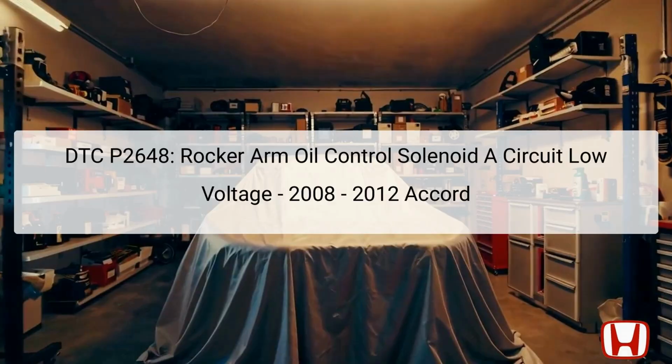The DTC P2648 indicates a malfunction in the rocker arm oil control solenoid A, specifically on the intake valve side, for 2008 to 2012 Honda Accord models. This code often relates to the vehicle's variable valve timing and lift electronic control (VTEC) system, which is critical for optimizing engine performance and efficiency.